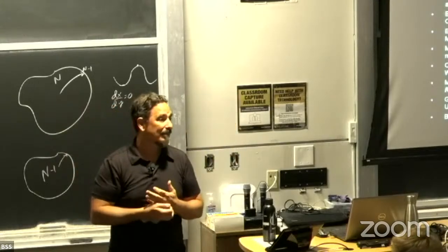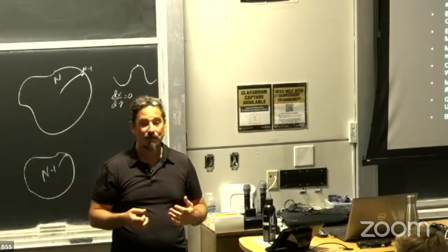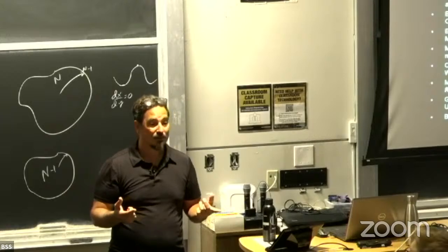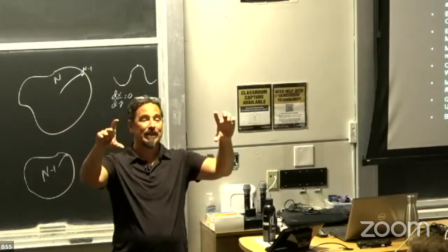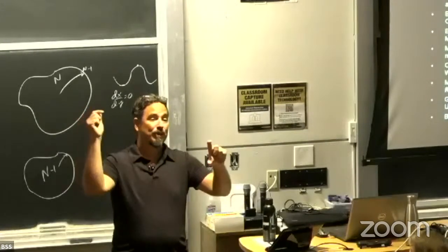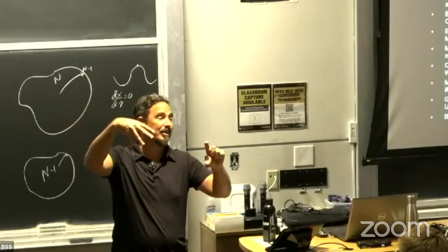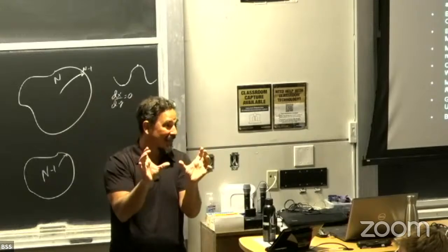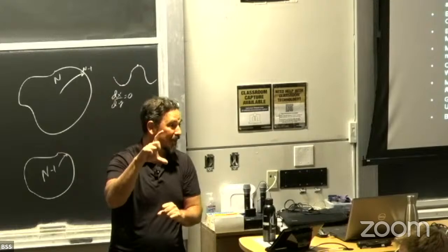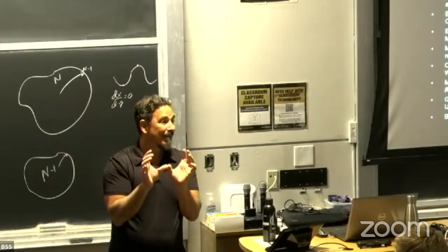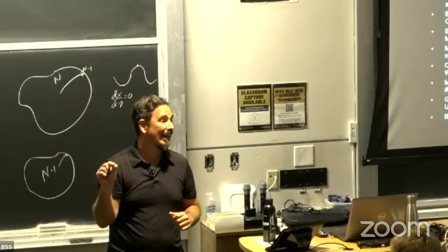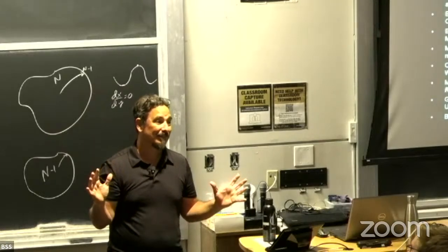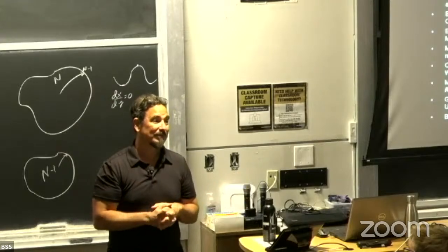To get around that and make something stronger, we had to use a bulk absorber of hydrogen. That's palladium. So our strong actuators are made half palladium, half titanium. You put a voltage on the palladium, and it absorbs hydrogen in bulk. Now the whole thing is absorbing and it has a lot more oomph, so you can make the film thicker and it still bends. And for a half micron actuator, we can lift a bumblebee. That's amazing, right? That thing is strong.